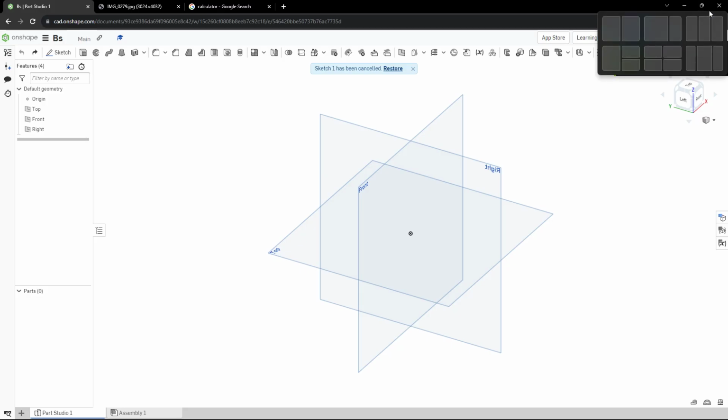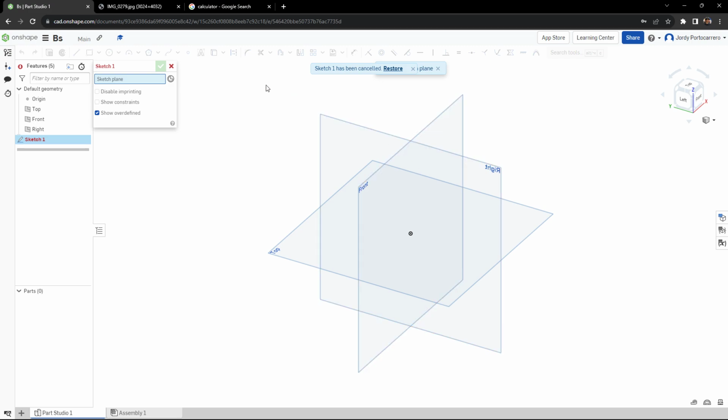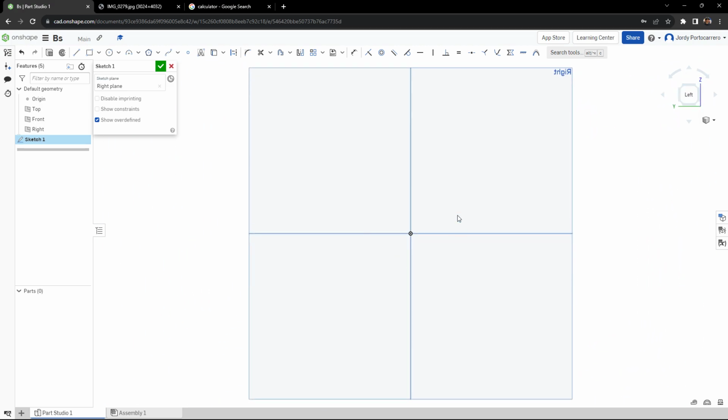Alright, well, I'm going to be teaching you how to do the sketch that we were supposed to work on during class. So, it's a pretty simple sketch. The only thing you really need to keep in mind is just the sketch tool. It's pretty self-explanatory. Just pick a plane you want to do a sketch on. Obviously, I'm just going to do the back. So, this is our plane to work on. You have the line, the square, circle, all this kind of stuff.